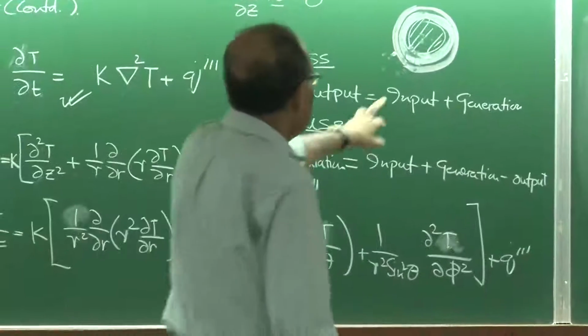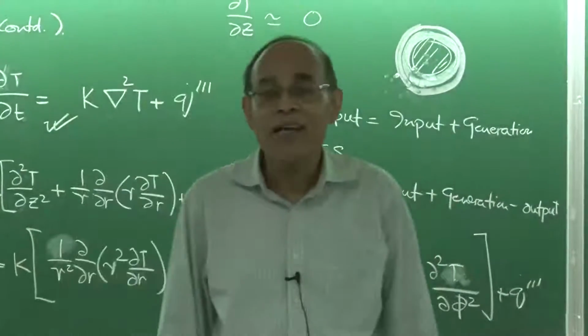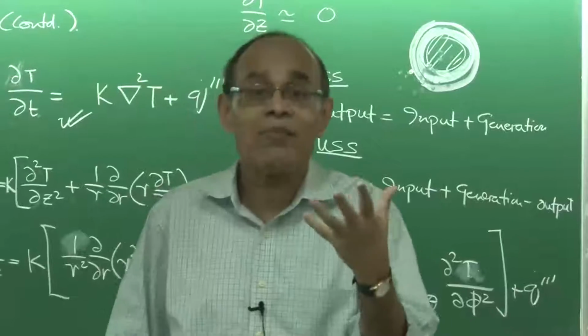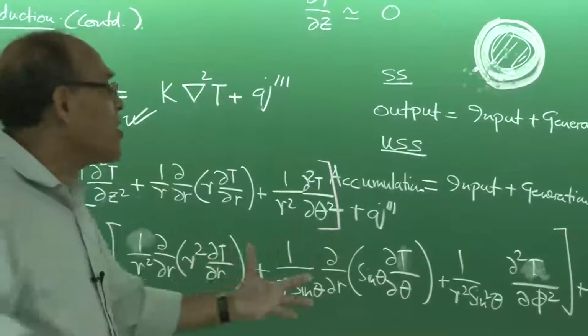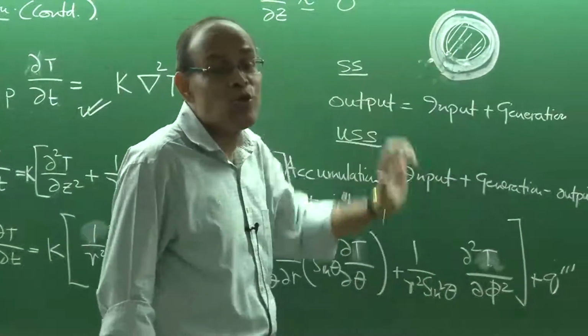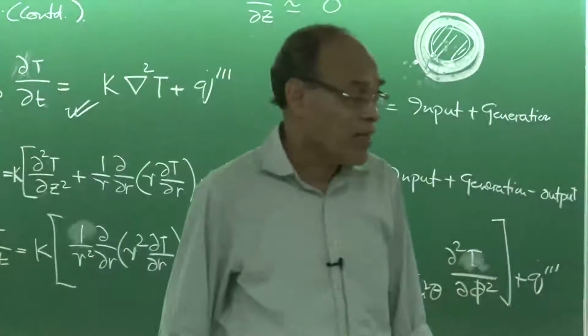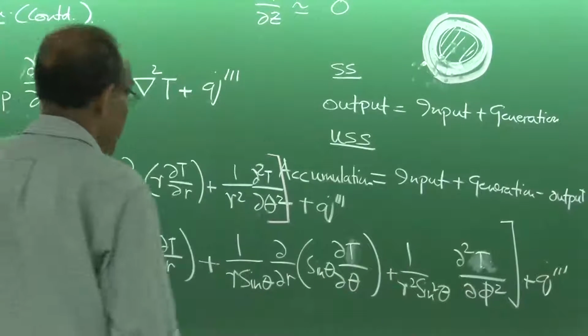And if you want to add the thermal contact resistance in such cases, you can do that, but again I repeat that the thermal contact resistance will have to be given to you. By summing up all the resistances operating in series, we should be able to find out the rate at which heat is leaving through any cross section.